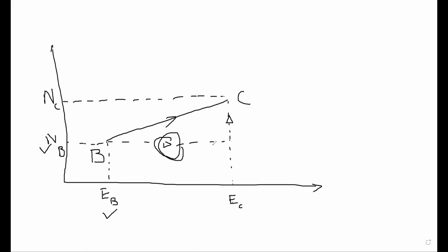If it is moving left to the right of you, it is positive. It is going left, it is negative. The value is there. So what you have to do, EC is EB plus delta E. So these sense have been taught before, right? So that's why I explained it separately. Otherwise, I have to explain in all the places, right? Now come back to the traverse sheet.